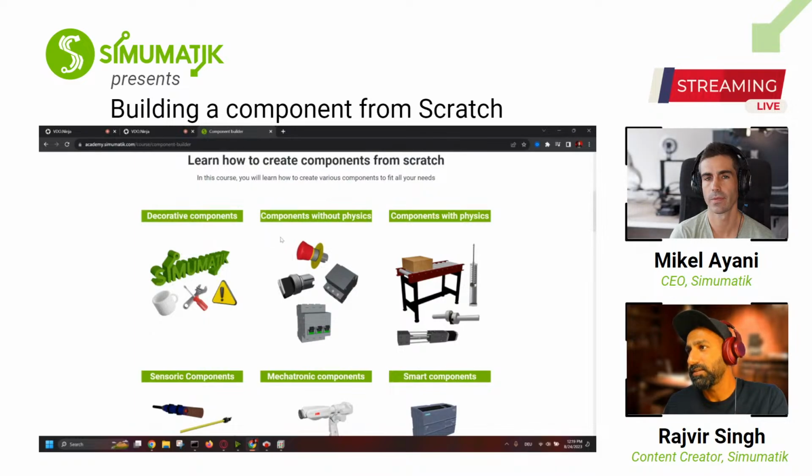The second category is components without physics, but with some behavior inside. For example, buttons, which can give you an electrical signal of 24 volts or 0 volts, or a circuit breaker, which will break the connection between the source and the destination. You can also make a motor contactor, for example, to energize the motor. So it has some animation inside, which you can define with the Python script, which you were telling about in the editor.